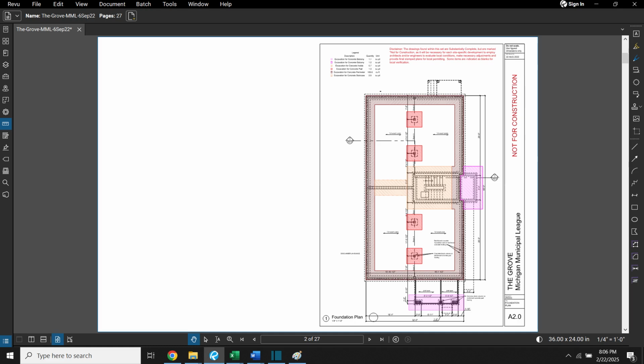Around central walls, the entire area is excavated for practical reasons. Purple shows excavation for balcony posts. Since most earthwork is already captured under crawl space excavation, the additional excavation for concrete is only 4 inches deep.